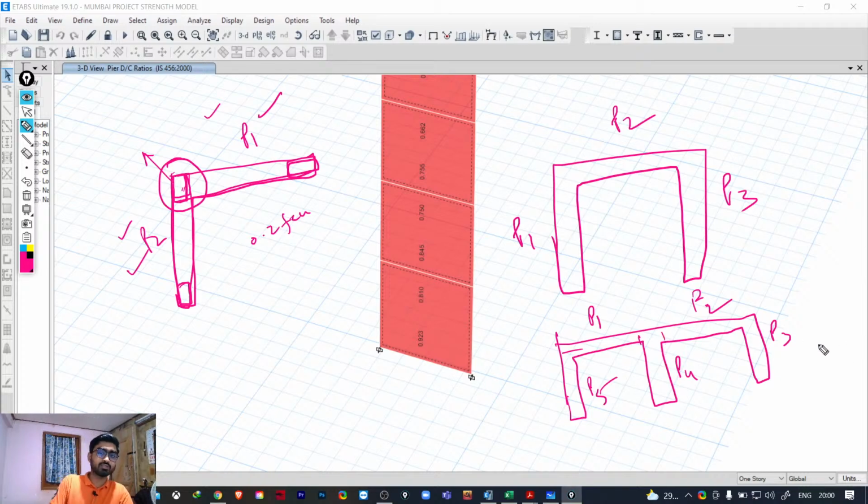Okay, now you just have to check what is the moment for all. Suppose these 3 shear walls are having similar moments, maybe plus minus some 5-10 kilonewton meter or something like that. In that case, you can go with the higher one and provide the similar reinforcement for all 3. You can check for these 2 and assign the maximum one to both. Okay, sometimes you need to go for value engineering also. That is a different thing.